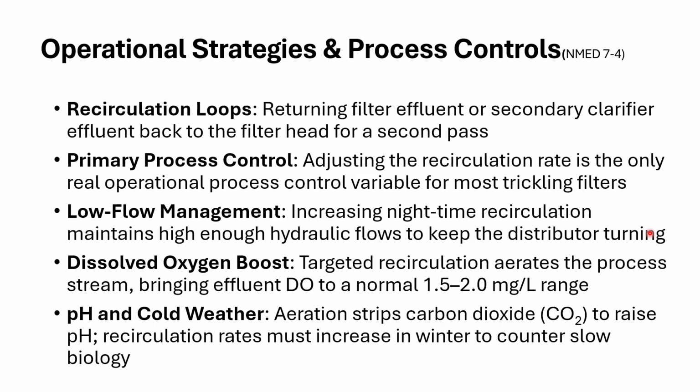So the idea here is during the night, we're going to increase that recirculation rate to make sure that distributor arm keeps turning around. Remember, I told you the force or the energy that moves that arm around is that trickle that comes down, that spray or trickle.